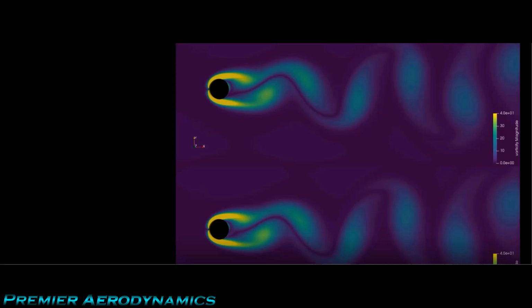So what you do is you go, okay, the dynamic pressure equals half times the density times the velocity squared. So I know the velocity, I want it to be 15 meters per second. And then you say, okay, well, the density I'm going to assume is 1.2 kilograms per meter cubed, or 1.225 kilograms per meter cubed, whichever of the two standards that you typically use. From there, you then calculate the dynamic pressure by going half times the density, 1.2 kilograms per meter cubed, times the velocity, 15 meters per second, squared. So you then get the dynamic pressure of 135 pascals.